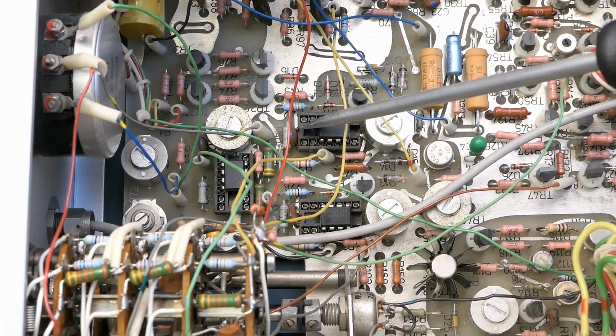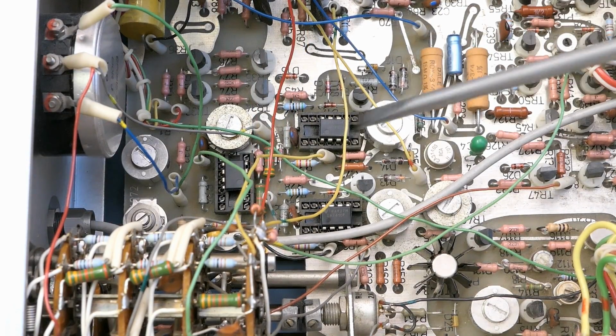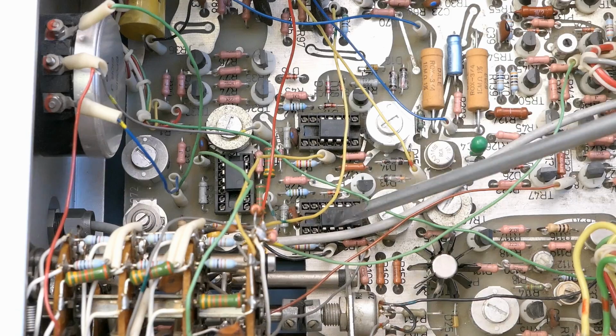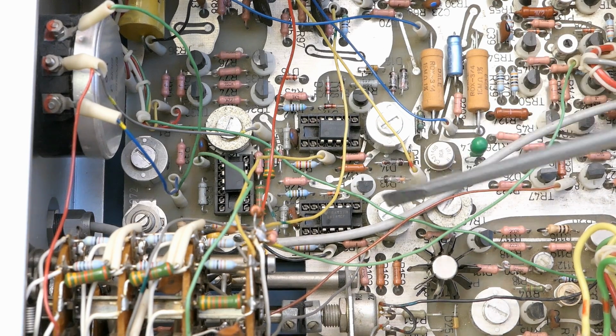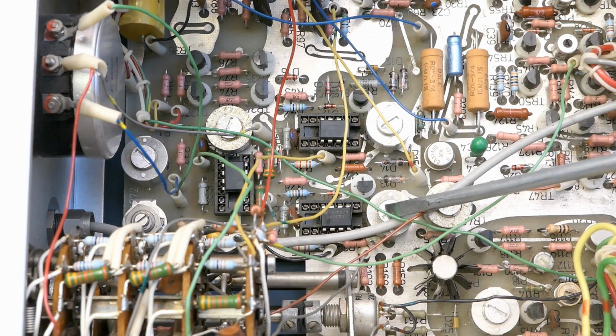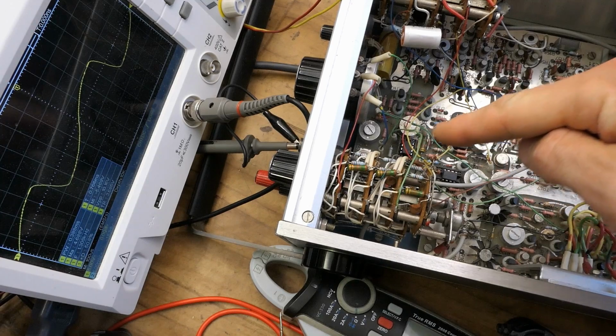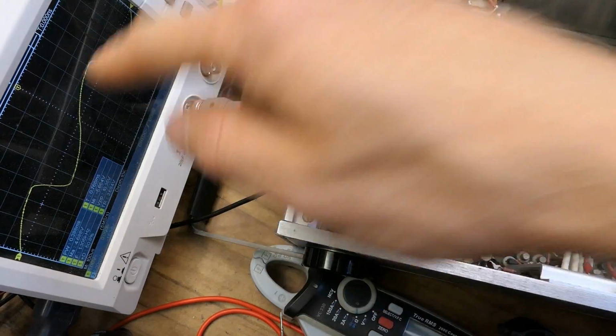And there are 3 identical op-amps, which if I try to rotate them, this one goes here, this one here, and this one here. If some of them is bad, moving them around will change it somehow. If it doesn't work, I will return them into the original positions because they might have offset null potentiometers for them. And then each of the potentiometers would be specifically set according to the offset of the particular op-amp. I rotated them and no change in the waveform.